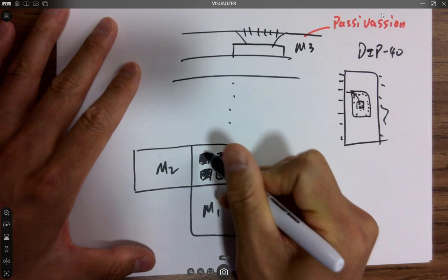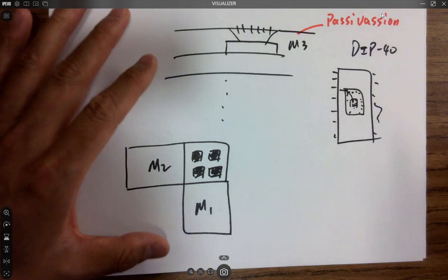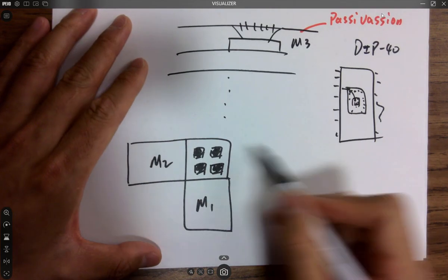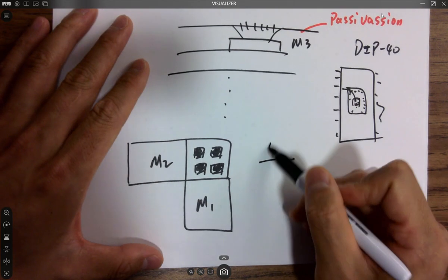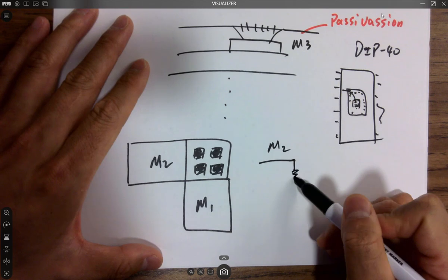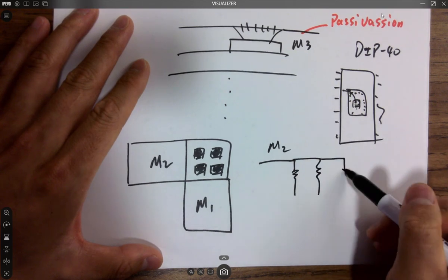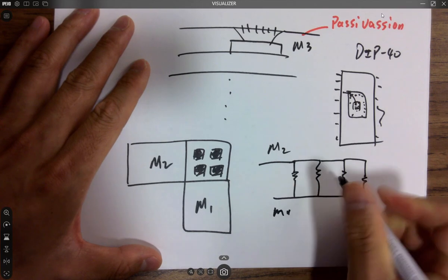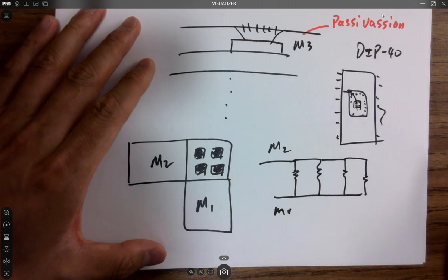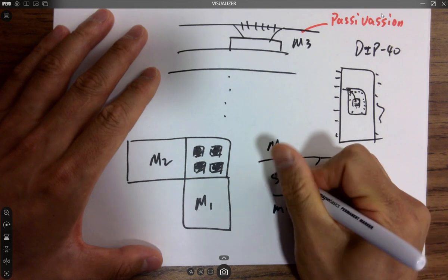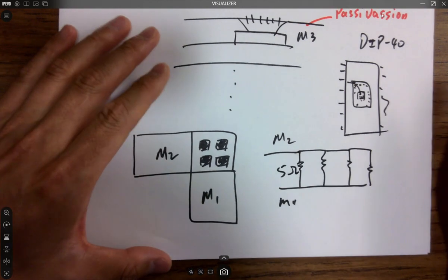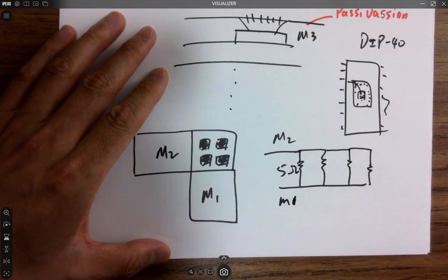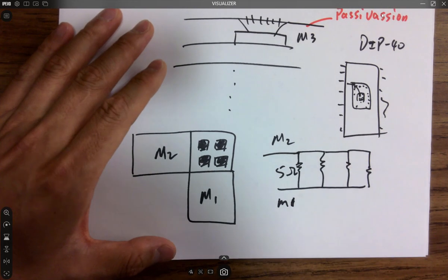Why that? Why not just one big via, but 4 individual vias? If you look at the connections, metal 2 wire, metal 2, every via has a certain resistance, even though it's a metal, right? But if you model the circuit, it looks like this. So these are the vias. Very low resistance though, I mean, 5 ohms or so. I guess because the parallel resistance would be less. Yeah, first the parallel resistance will be smaller. Good.